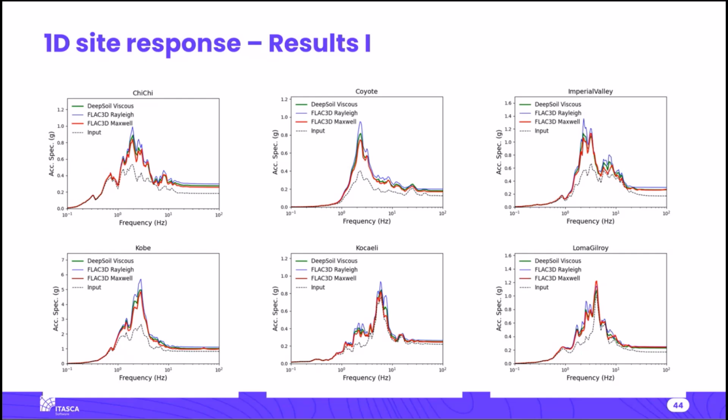Here we just use the DEEPSOIL result as a benchmark. It does not mean that it is the physically correct result. And if we look at the Rayleigh damping, some results are higher than the other 2. But usually we didn't find any significant phase shift for these problems.